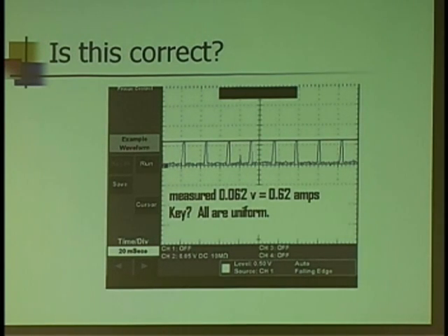And that's all I'm doing here, I'm measuring the current through all the injectors at the same time. If I have one that starts developing an electrical issue, when do they usually fail? They're either going to go bad completely or they heat up. Now, this is what I talked about before about using your trigger as a diagnostic aid. What if I'm looking for a problem and I suspect there's going to be an issue with one of the injectors falling out and the resistance is going to go up, so current's going to do what?